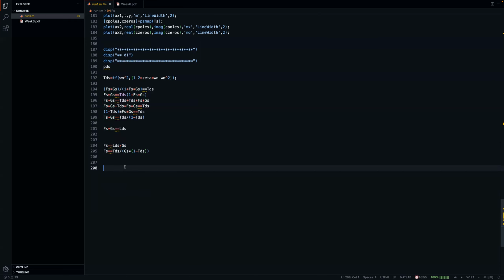So until this point, we've seen some partial pole zero cancellations. But today we've seen actually that all the poles are going to be canceled out with the controller zeros. And this is exactly the same. So it takes the inverse of the system, if it's invertible, and then it uses it as a structure. It's the part of the controller, and adds more to it in terms of poles and zeros, and that's going to be the controller itself. Or in other words, it converts the closed loop into open loop and then uses that open loop divided by GS because it should get rid of GS entirely.